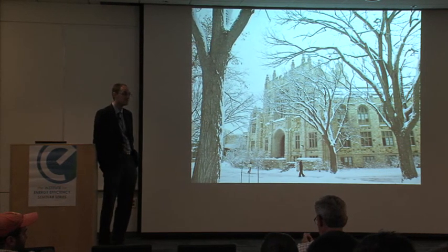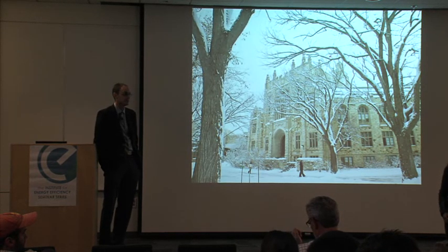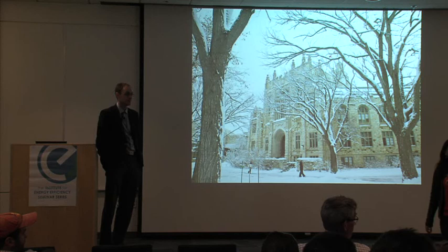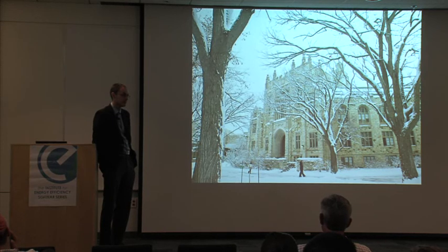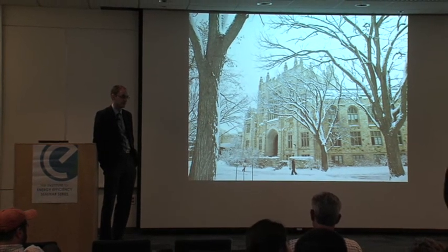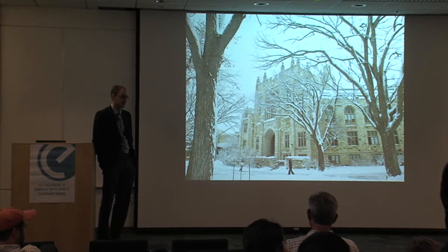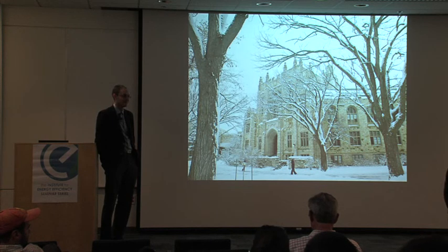I have two questions. First, is it possible to dope these perovskites? Is it possible to prepare a PN junction based on perovskites since it's inorganic material? And second question regarding the instability caused by the zinc oxide layer. Maybe the issue is from the way you prepare it, not directly from zinc oxide. Did you try to check this instability with zinc oxide deposited by magnetron sputtering, so without any residual chemicals?